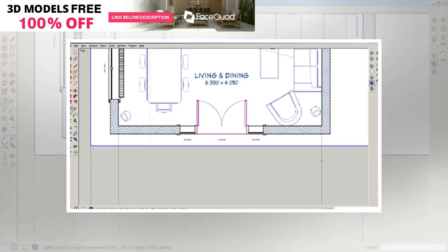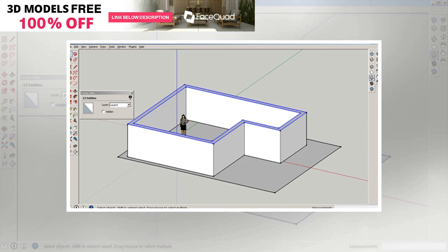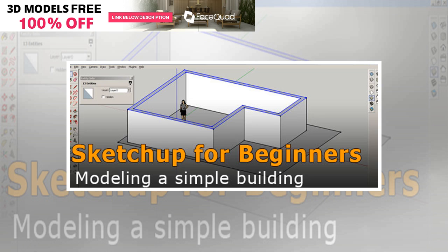When you type dimensions in default units, you can omit the unit sign. For instance, if your default units are inches, you can just enter 2'6" and SketchUp will interpret this to be 2'6". But you need to type 700 mm because mm isn't the default unit. Turn on and set up length snapping to be 10 mm or 1 inch to avoid fractional dimensions, like 2567 mm, when drawing with the mouse.